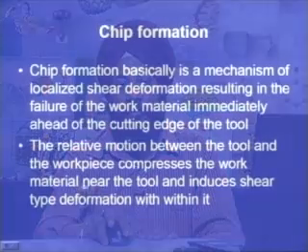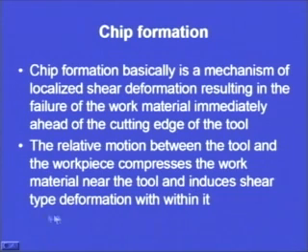So, the relative motion between the tool and the workpiece compresses the work material near the tool and induces shear type deformation within it. So shear type of deformation will be induced in the workpiece material.